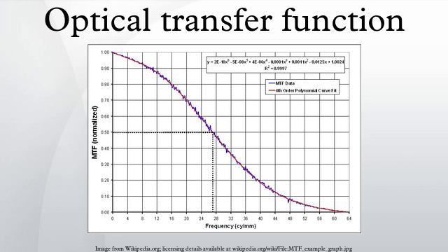Digital inversion of the optical transfer function. Often the contrast decreases significantly before the Nyquist frequency of the display is reached. Digital image deconvolution is the procedure that reverses the contrast reduction to yield a sharper image. Errors in the recording due to noise or aliasing will also be amplified. The technique is thus only effective on high-quality, high signal-to-noise ratio recordings.